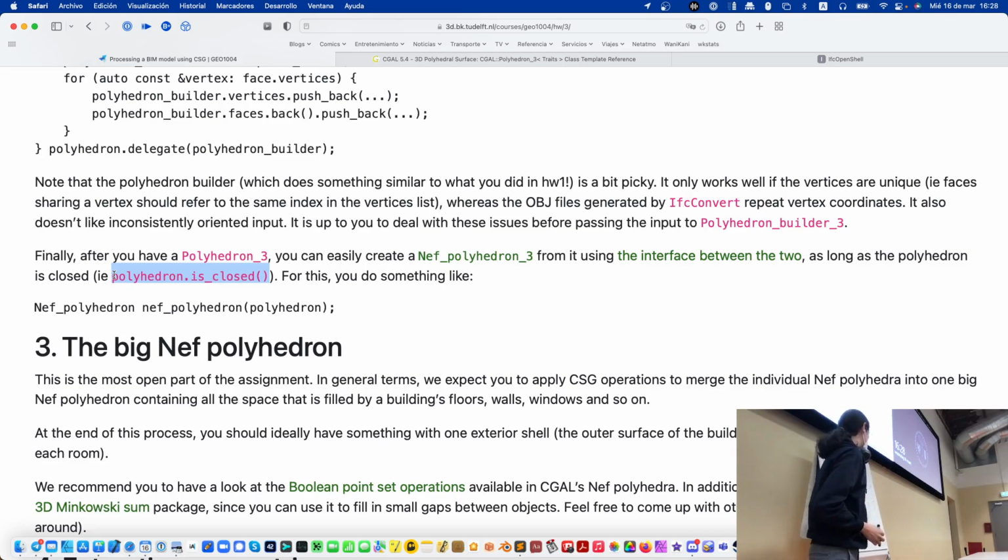In practice, this can also be checked by the vertices for the face. So this thing that I mentioned, the edges should always be present in opposite orientations. They should also just be present twice. So an edge from 1 to 2 should be present twice, once from 1 to 2 and once from 2 to 1.